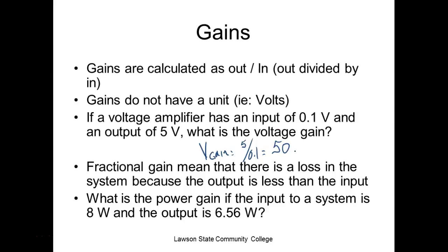No, we're not even to dB. 50 is a multiplier. And this gives people problems. I'm talking about voltage gain, and for some reason they want to give this multiplier a unit. Gain has no unit. It's just like if I said, I'm going to triple your salary, and he says, oh, that's great, I'm going to get a $3 an hour raise. No, you don't understand that. It's a multiplier.